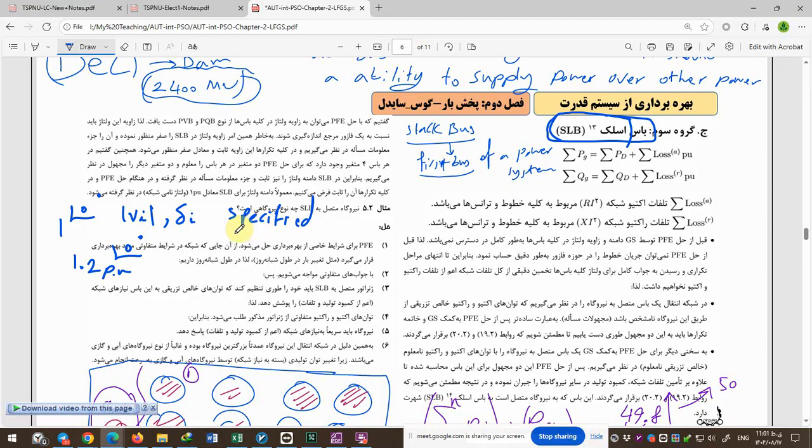A slack bus acts to compensate the amount of power, which can be not more than the bigger one, and its size is not important, but the ability of a slack bus to fill a small gap, to fix the frequency and help to improve your grid stability.